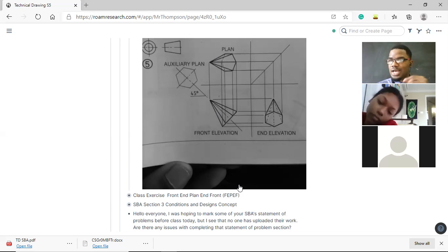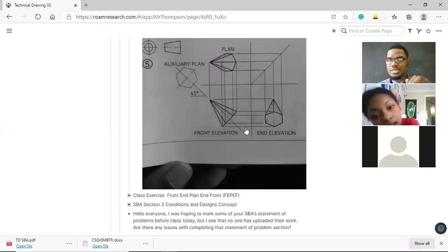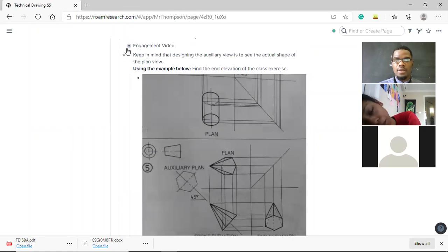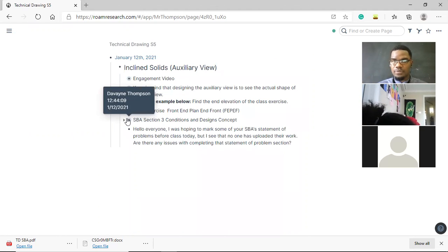So it's a quick little acronym to remember which projection symbol you're doing. Whenever you see only plan above here, you know that's third angle projection. Whenever you see the front and the end above here, that's first angle. Hence why you see FE first. All right? Yes, sir. That clears it up. Okay. But what I want you to know how to do, because that's really the portion I want to focus on,